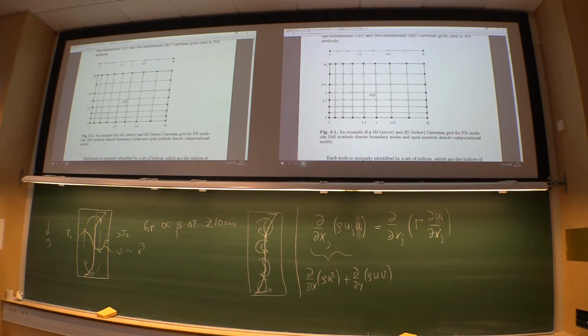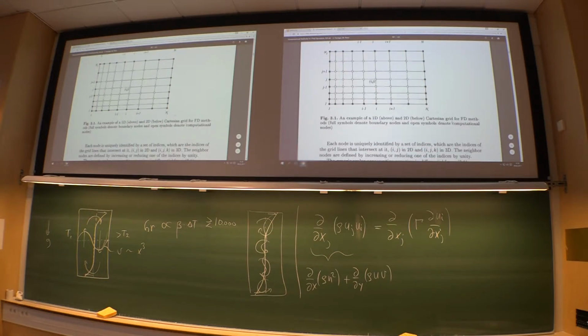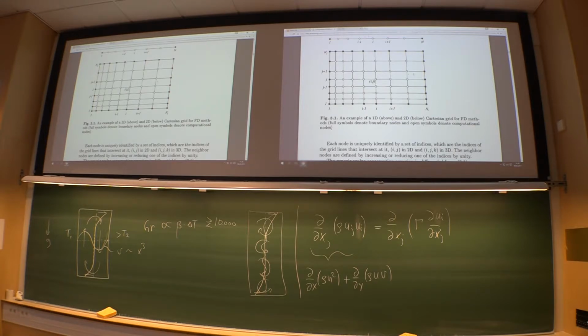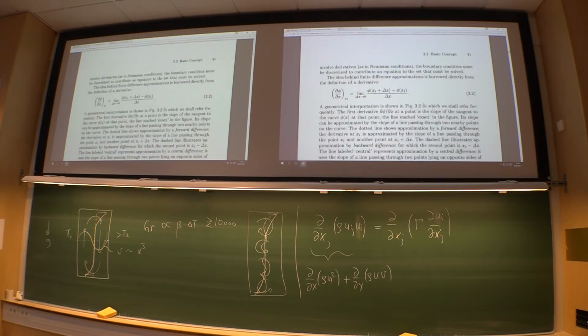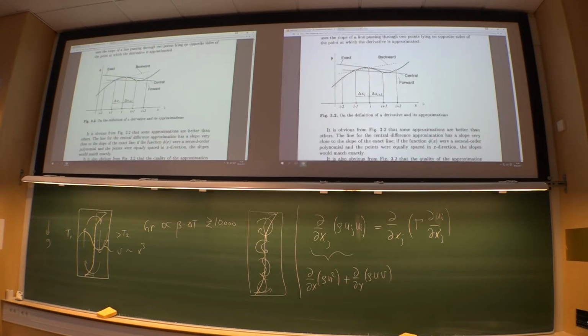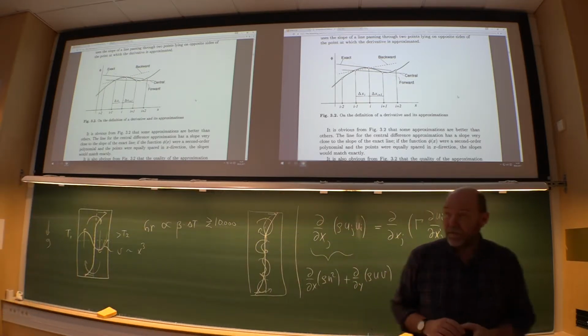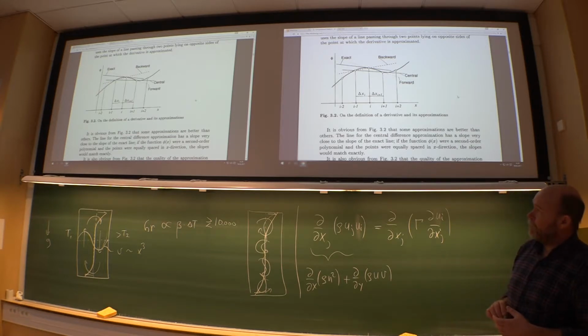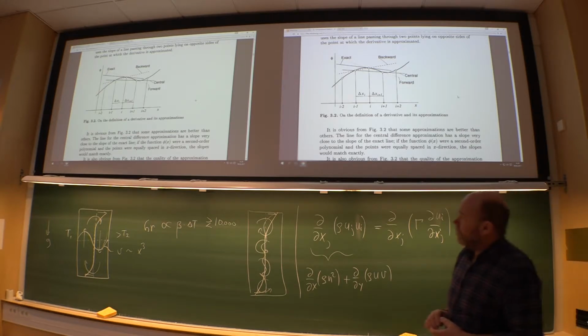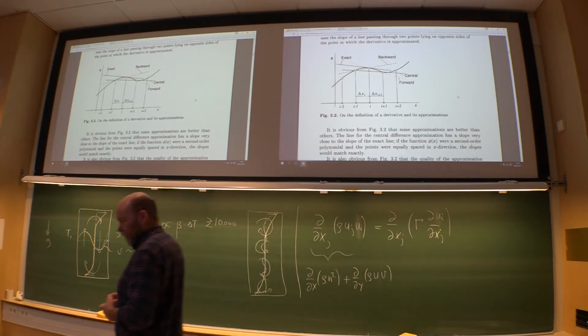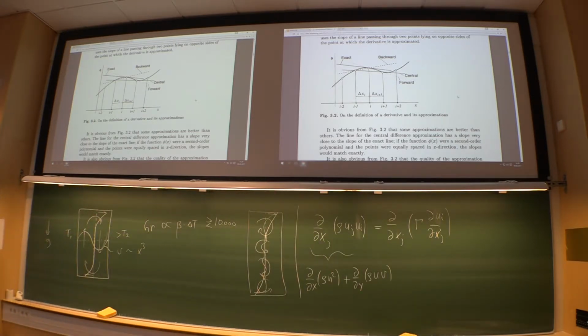So here he talks also about mesh systems. Here all the unknowns are put in the corners. But as you have seen, staggered mesh systems are also something that is used. Now, looking into finite differences, you have central differences, you have backward and forward. So the central definitely looks more like the exact one, but backward and forward differences might be useful sometimes.